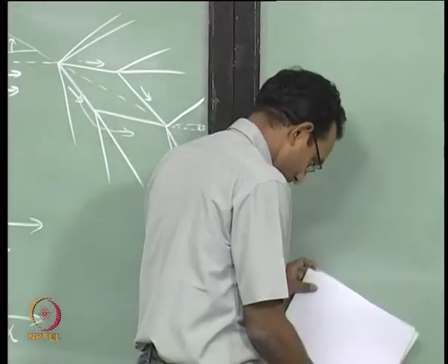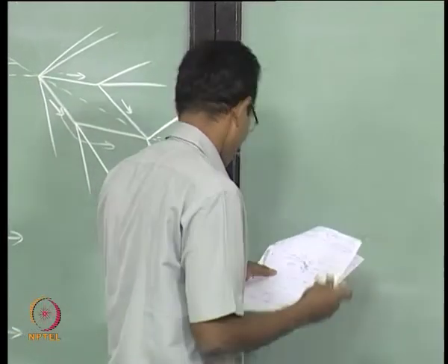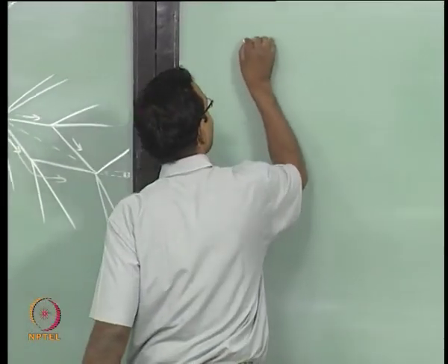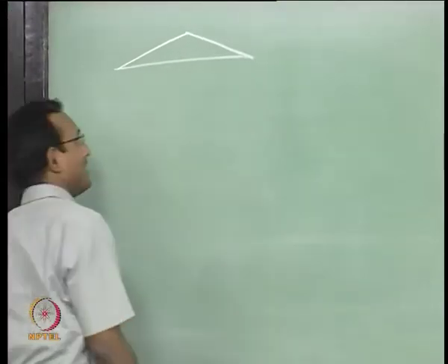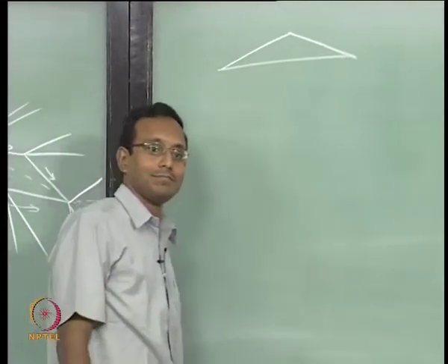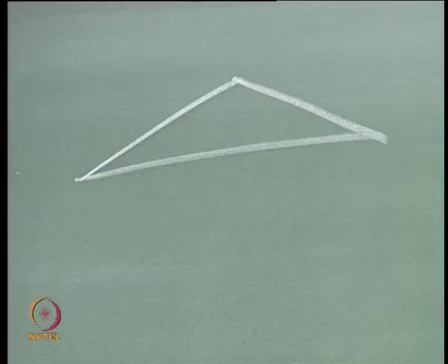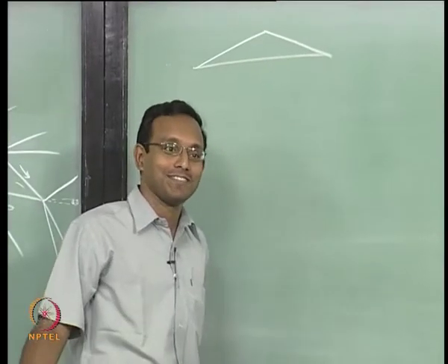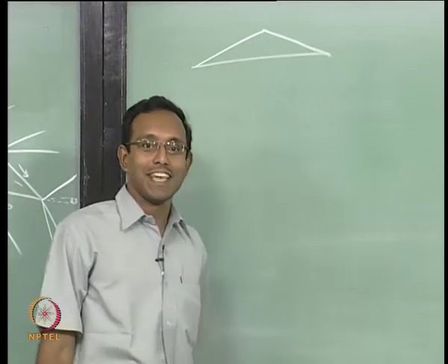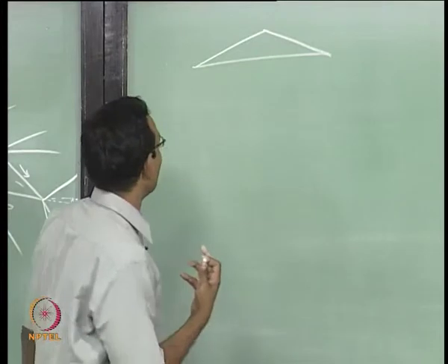Now I want to pick up some other flow situation, more complex stuff. Let us take a case where it is half of that diamond airfoil. Will this produce lift? Why? From an aerodynamics point of view, it has a camber. A cambered airfoil will produce lift.